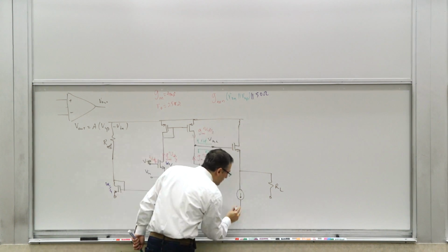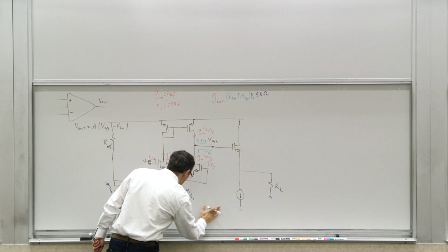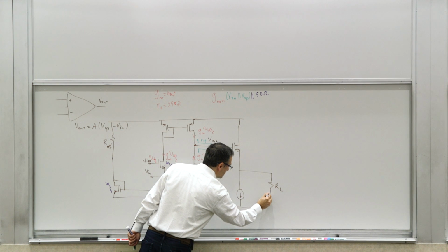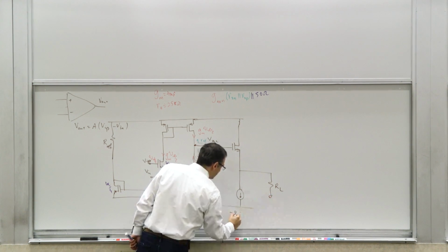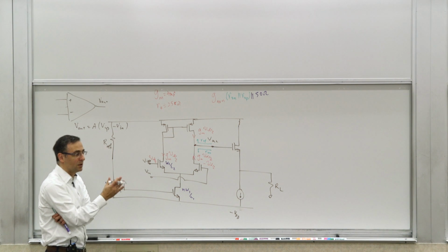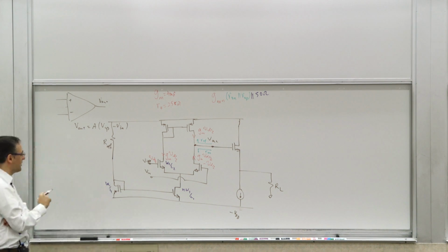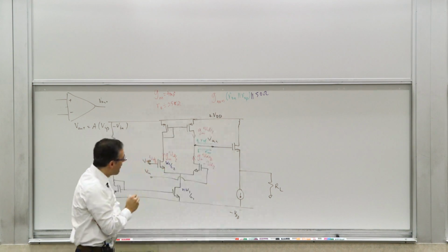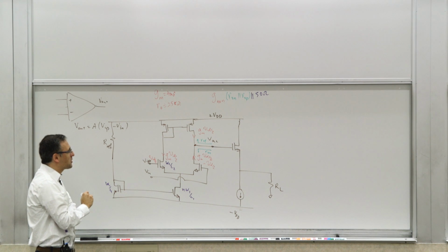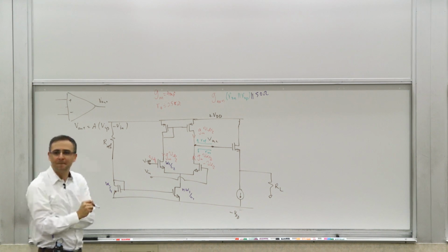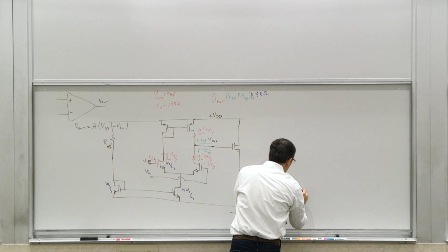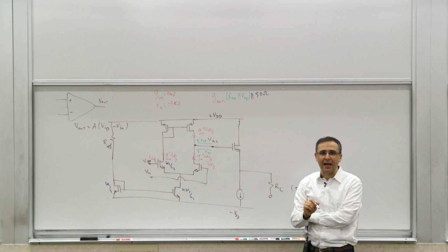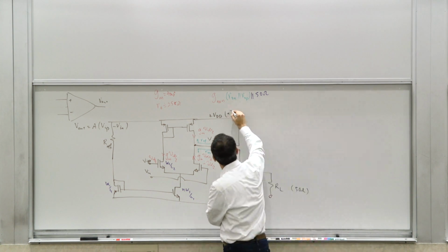Now, if I do a source follower, I have limitations of the source follower, right? I have to worry about that. So let's make this another rail. Let's say negative VDD. Let's say it's a bipolar or two-sided supply. Now, okay, so let's say my load is 50 ohms, for the sake of argument. If I do this, and I want to be able to do as close to a full swing as I can. Let's say my supply is plus minus 3 volts.